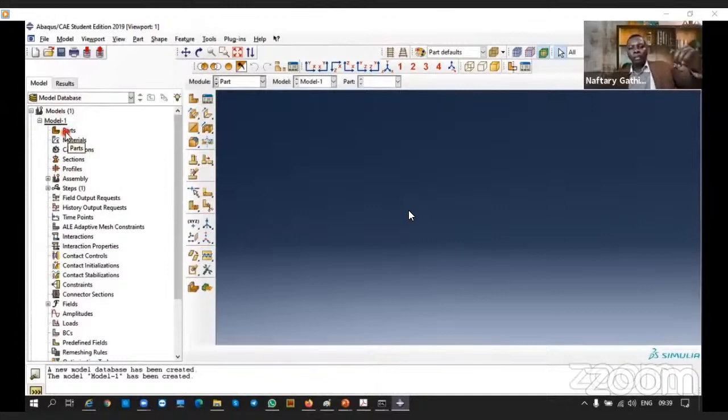Remember the same way we said for finite element analysis, we start with selecting the element type, you discretize. There was a certain procedure for all the examples that we covered. Even here in modeling, you create the model, so you create different parts. Then you have to define the material for different parts. Maybe you have a composite structure, where maybe a concrete, the steel decking. So you have to define for different parts what are the materials. Now for the different sections, you have to define a section like steel section, the concrete section, and then assembly is when you bring them together to make the structures work as one.